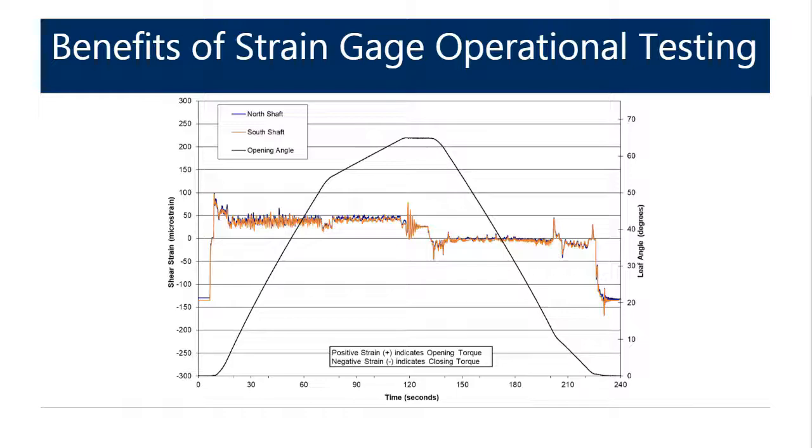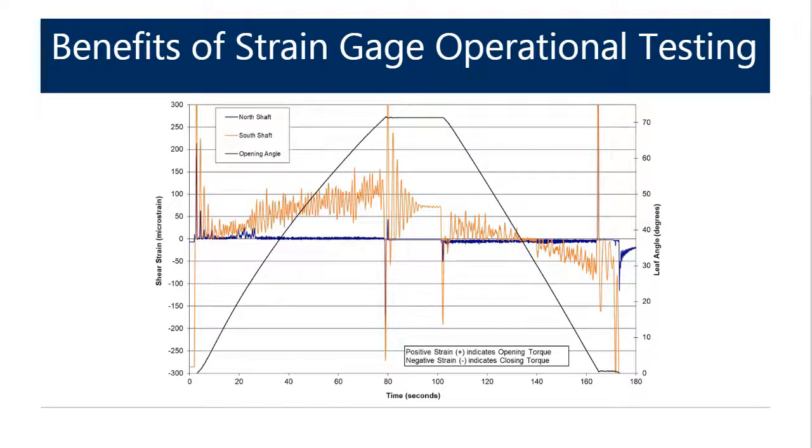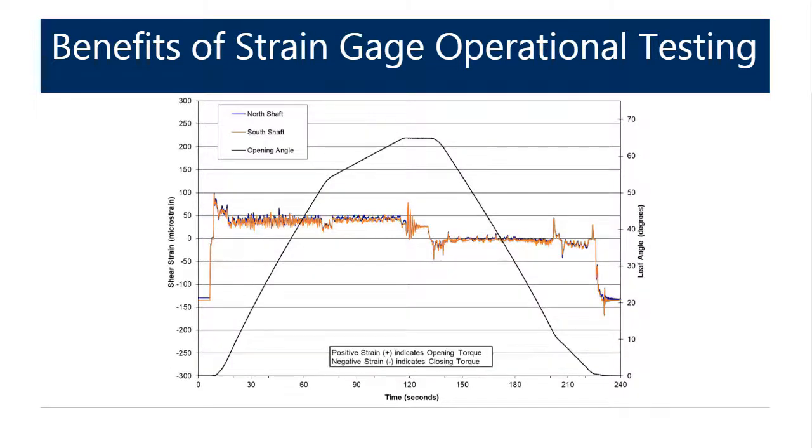This demonstrates a clear benefit of strain gauge testing when you're seeing machinery loading. Again, I want to reiterate, this is the initial condition we found the bridge at and the final condition of the bridge. So yeah, clear benefits for determining operational loads on your machinery.